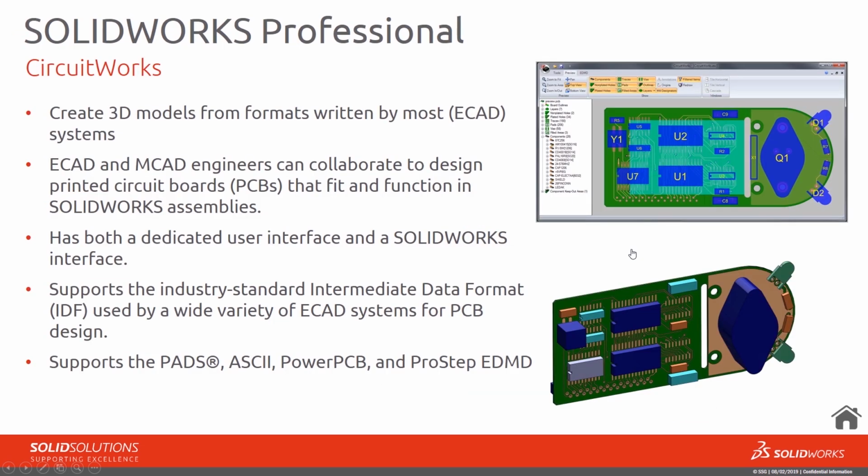We've also got CircuitWorks as well. So that's allowing basically conversions or collaboration between ECAD, which is electronic CAD, and MCAD, so that's mechanical CAD as in SolidWorks. But it just allows the ECAD and MCAD guys to work in collaboration to do things like fit and function. Also being able to generate 3D geometries from your IDF files.